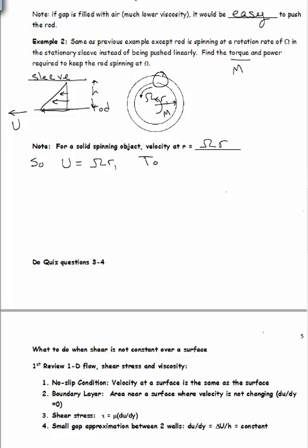Okay, and our torque equals our moment, which is going to be M, and it's going to equal F times r1, because our tau here is going to act as tau wall in that direction. So this spinning shaft, spinning through the fluid, is going to pull back on that shaft in that circular omega or theta kind of direction.